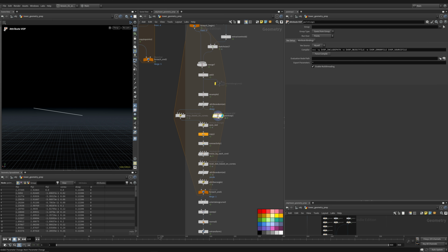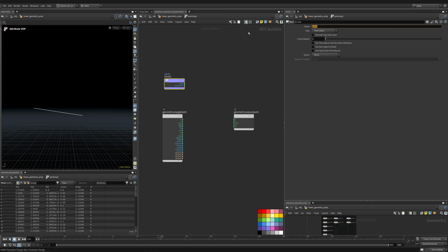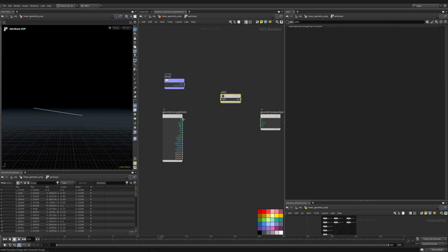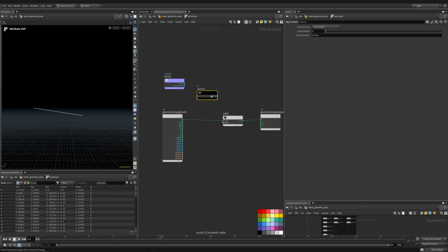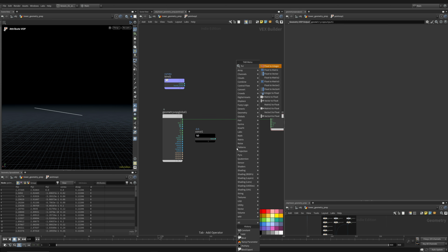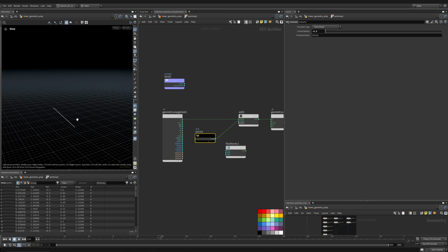The way I'll do that inside this VOP is I will take a bind, which, remember from the grass video, we need our curve view, and we need an add, because we want to take our position and add a value to it. And we'll do a constant. So right now, if we just add, and I'm going to middle mouse button and drag, now we're adding a float to the vector. So I'm going to shake to disconnect, and we'll do a float to vector. If you see, and I'll connect that again, it added this 0.5 value to the X, the Y, and the Z.